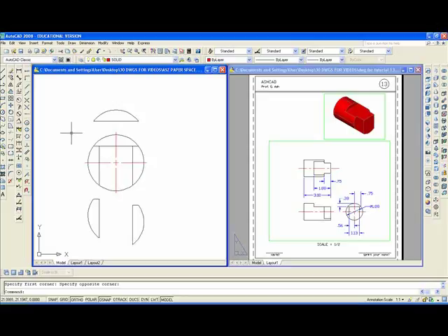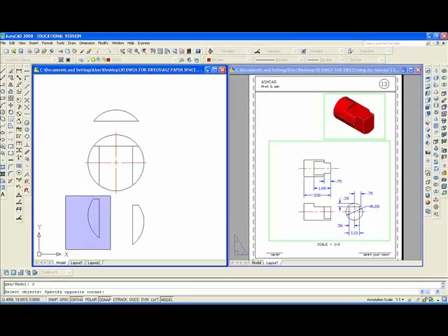First, I think what I want to do is polyline edit. Make that a polyline, yes. J, enter. I'll select both lines. Hit enter twice. Repeat the command. Polyline edit this line. Yes. Join, enter, J, enter. Select everything. Enter twice. And do the same on the other side. Polyline edit. Yes. J, enter. And select it twice.